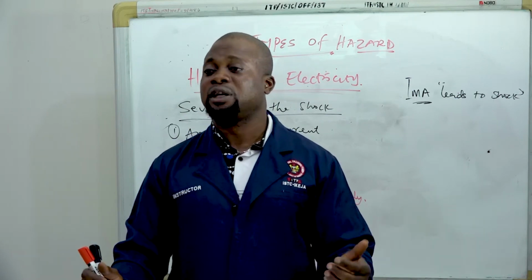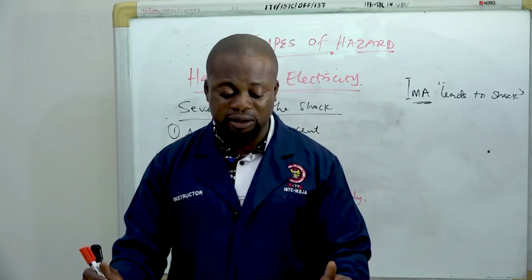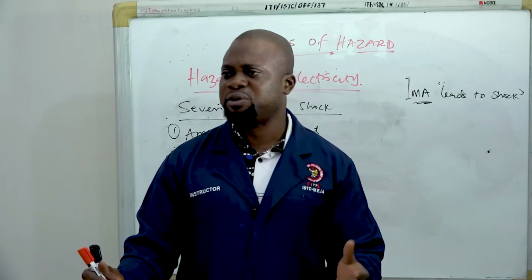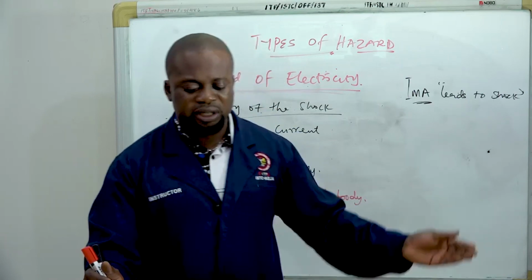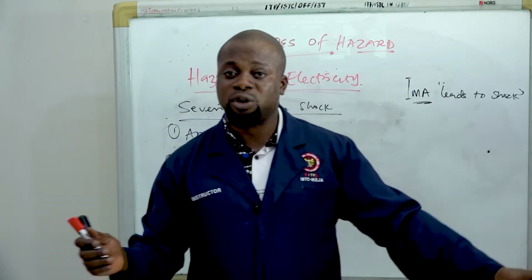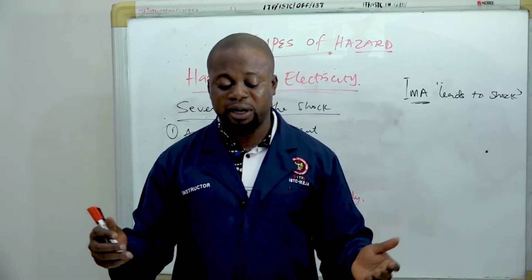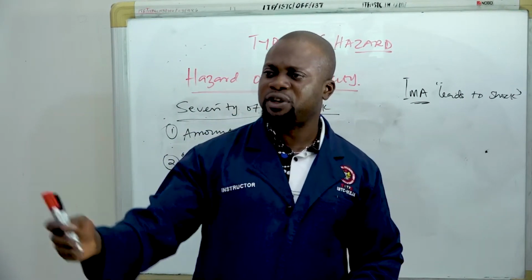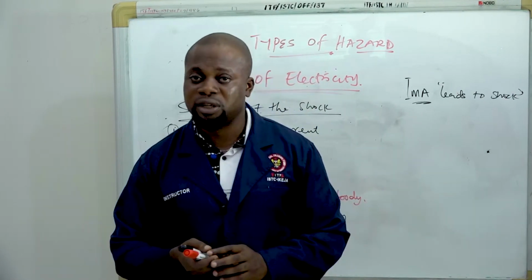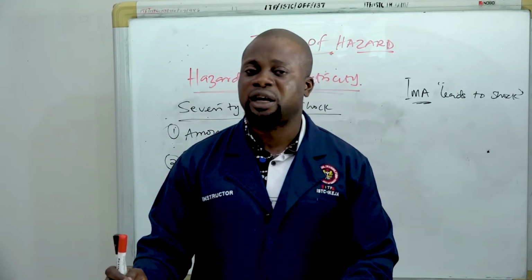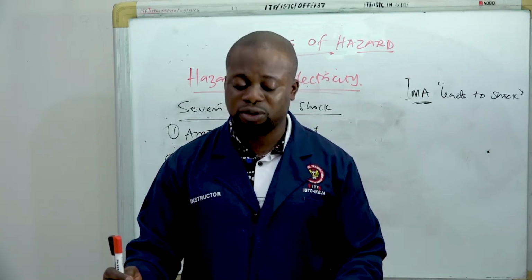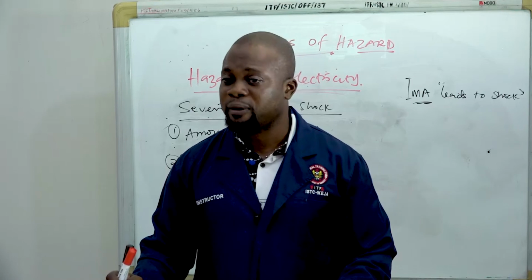We looked at the arc flash, the arc blast, and of course the physical hazards, like the wet environment, cables littering the floor, walkways and doorways if not properly installed, lifting objects, and stretching the body unnecessarily. These are the types of hazards we need to consider to work safely.